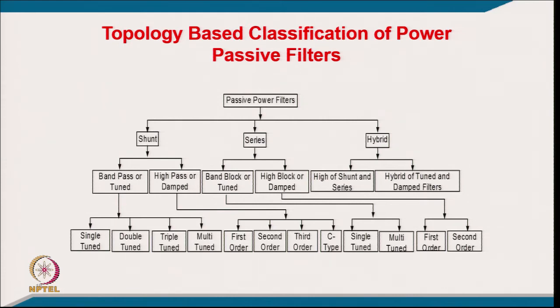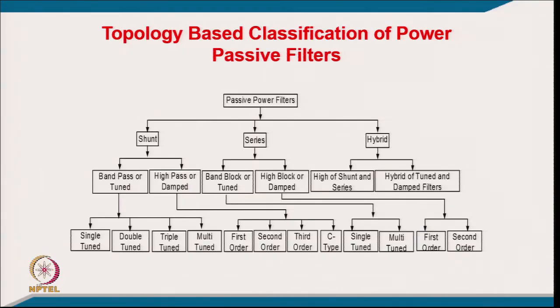So, that is about the shunt filter, which we normally prefer to use with the current fed load. Current fed load means where you have a reactive power requirement as well as harmonics, like a thyristor converter used in HVDC, as I have given an example, as well as the thyristor converter for DC drive. Or a thyristor converter with AC supply is used with a large inductor to derive a current source for a current source inverter or a load commutated inverter for very high power rating drives, typically up to 75 megawatt synchronous motor drive. So, that is about the shunt passive filter.